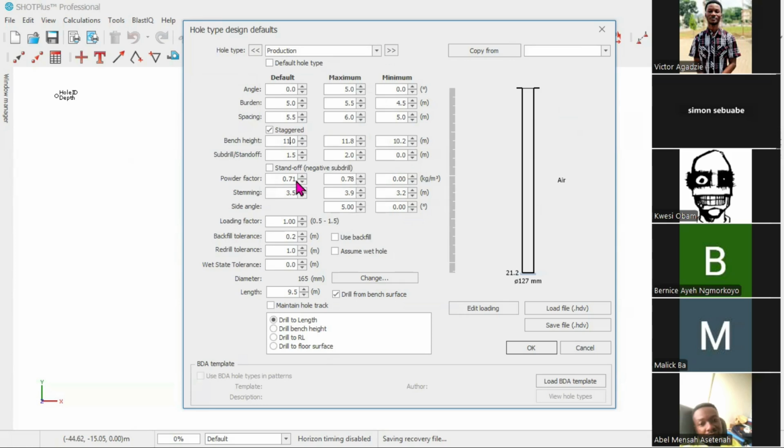So okay, but still, Benis, let's assume Benis is pumping. Benis, how much explosive do you want to pump in each hole? 11 meters is quite deep, so 50 kg, or 45, 50 kg. 50 is small. It's very small. So okay, Benis, let's say you are pumping 150 kg of emulsion.